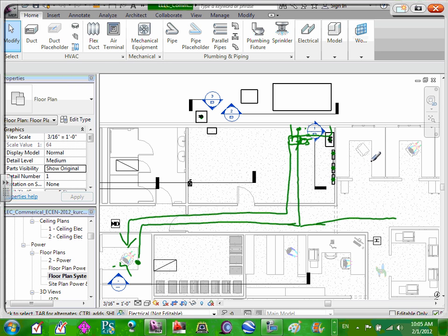Because the sprinkler system might know there's a fire before your fire alarm system knows, because we have smoke detectors, and essentially a sprinkler is a heat detector. It might know that there's a high flame fire before there's any smoke that can even reach one of the smoke detectors. So it's another way of getting a signal to that fire alarm system that there is a fire in the building.